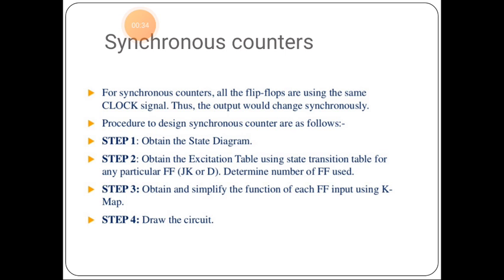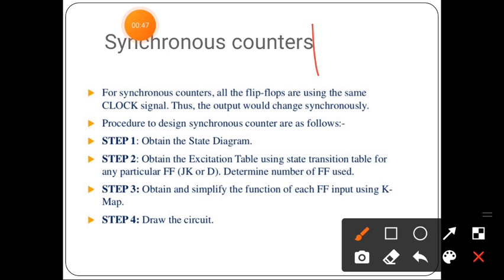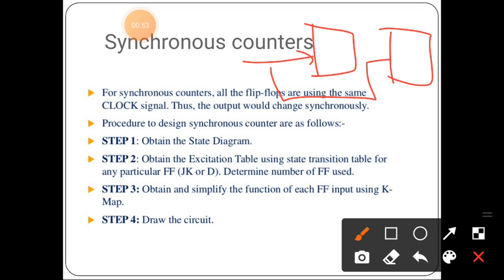But in the case of a synchronous counter, all the flip flops use the same clock signal. The output would change synchronously. That is, if there are two flip flops, then the two flip flops are triggered synchronously because the same clock pulse is applied to both flip flops.